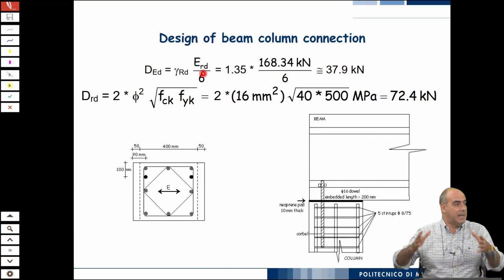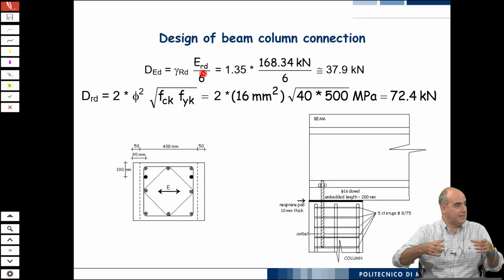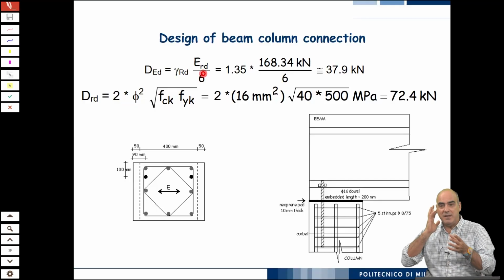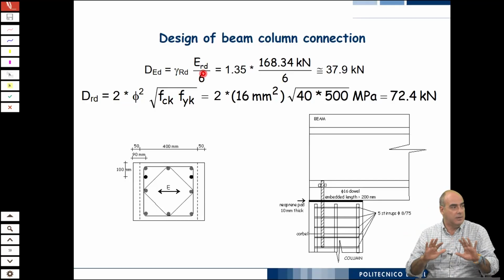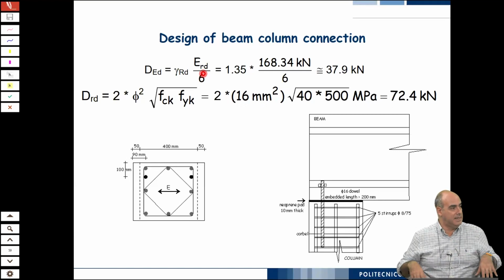This means that you have the diaphragm action of the roof deck. But this roof deck was made by 3 beams and 3 plus 3. Yeah, so it was something like this. So really, the diaphragm action, as we have seen in the model yesterday, is all due to the connections. If one of them fails, you will start having this element here move strangely.